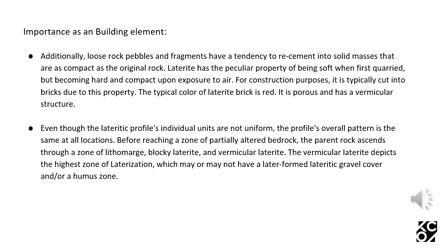Moving on to importance as a building element, loose rock pebbles and fragments have a tendency to re-cement into solid masses that are as compact as the original rock. Laterite has the peculiar property of being soft when first quarried, but becoming hard and compact upon exposure to air. For construction purposes, it is typically cut into bricks due to this property. The typical color of laterite brick is red.